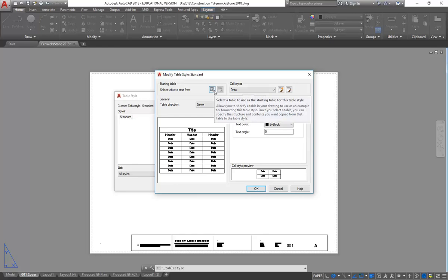So, if it's greyed out, that means you've set a height in the text style. So just click the browse button next to where it says standard, just down below that, with the text style. Down below it says browse button, and then you just change the height there to 0. And then turn off annotating as well. And then just apply.